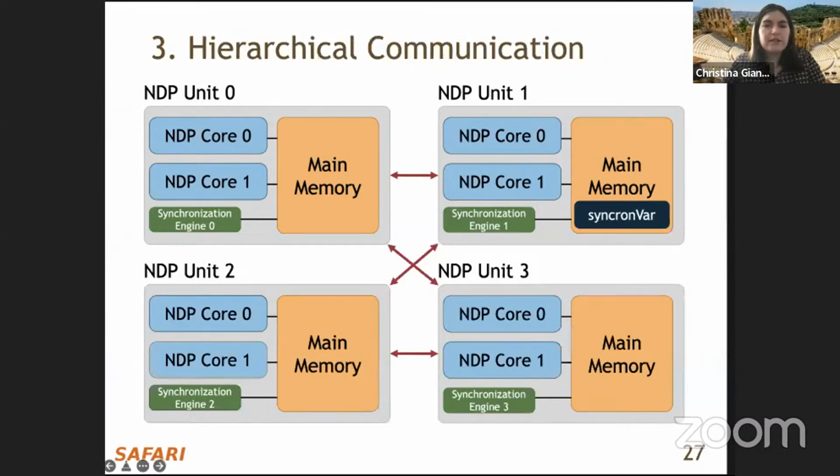SynCron organizes the communication hierarchically. For a particular synchronization variable allocated in an NDP unit, the synchronization engine that is physically located at the same NDP unit with it is considered as the master synchronization engine. The master synchronization engine is responsible to globally coordinate synchronization for that specific variable.